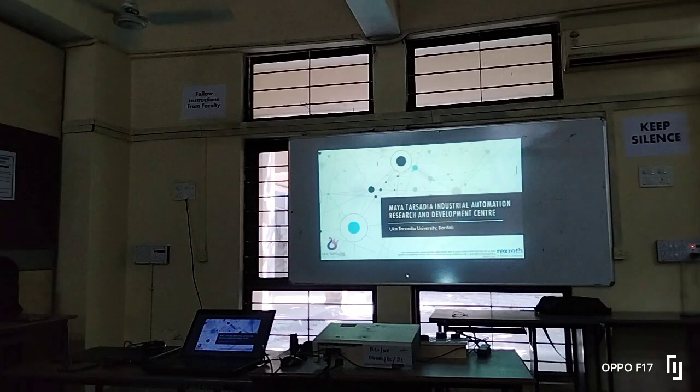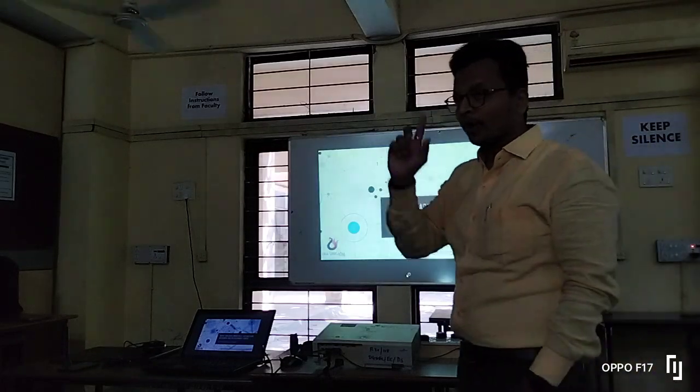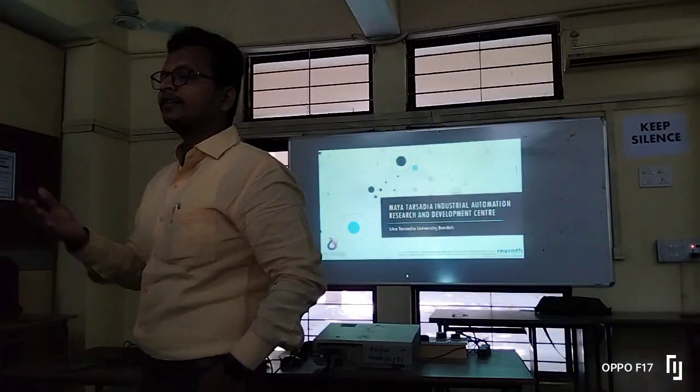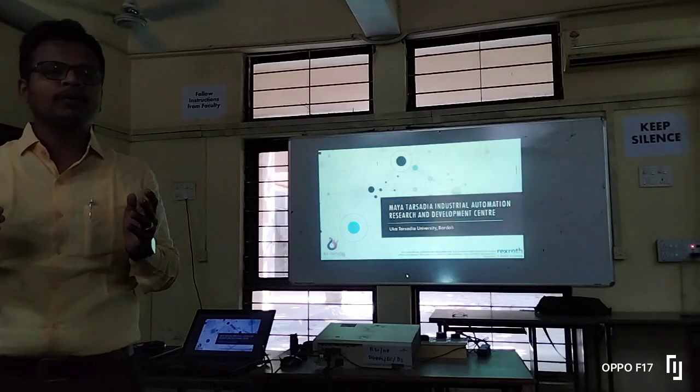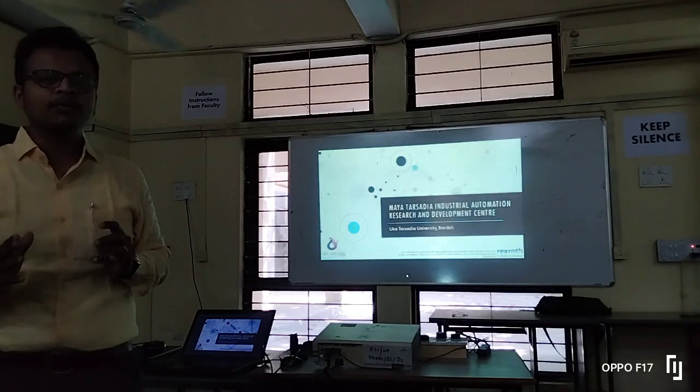Which type of operation we want to perform? Out of that 12, what will be the input? What will be the output destination? So that selection will be based on that particular control word. And that control word is nothing but your instruction. So from that instruction, we'll decode which kind of operation the processor has to perform.